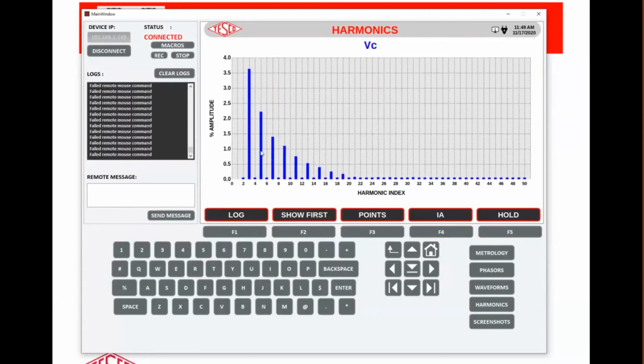And this happens typically because the potential transformer, if you're operating a PT-based service, can't handle the crest factor of the current that's being drawn. And so you'll get a dip right at the peak of the voltage waveform.